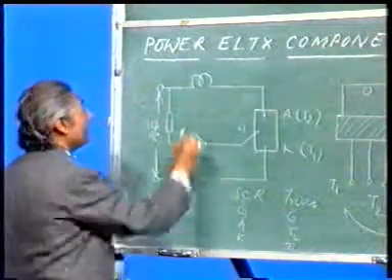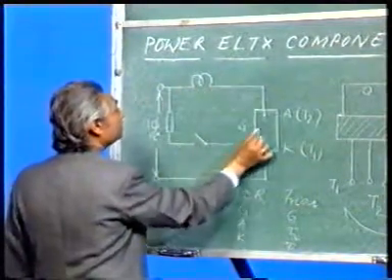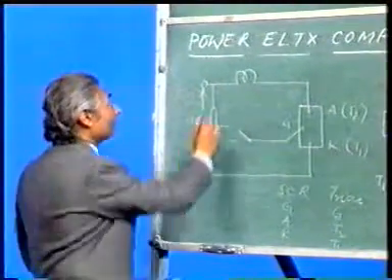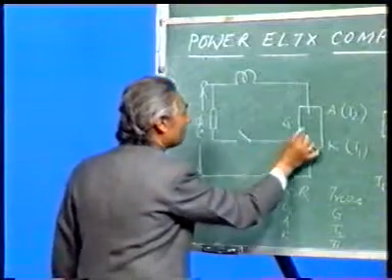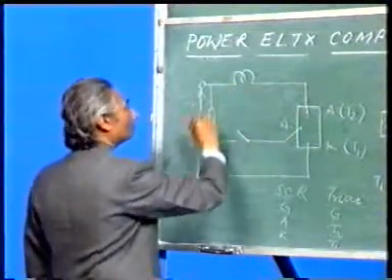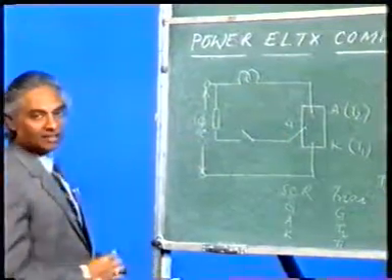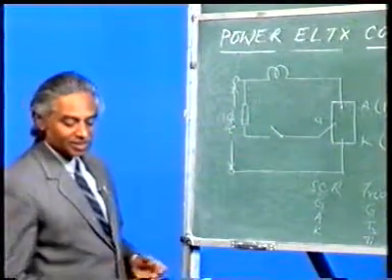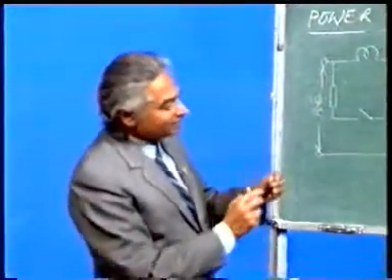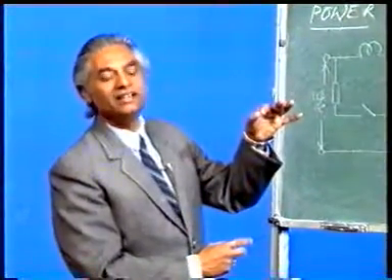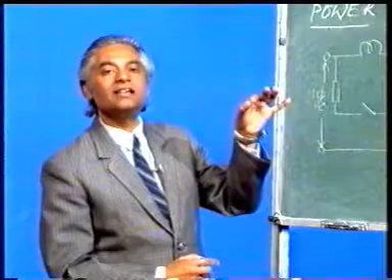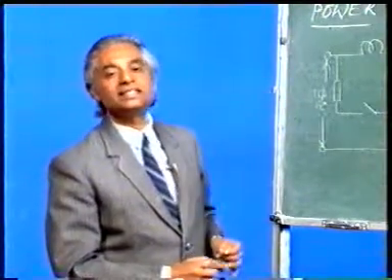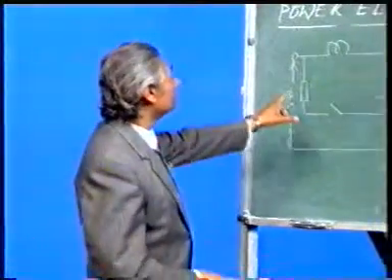But if I have connected it like this and not given the gate supply and it starts glowing, that means the device is short. Again, if I have connected it in this fashion, given the supply also to the gate, and the bulb is not glowing, that means the device is not conducting, it means the device is open. That is true. But sometimes suppose this print has faded. So it will look like an SCR or triac also. You cannot identify which one is Triac, which one is SCR. For that also this particular circuit is going to help you.